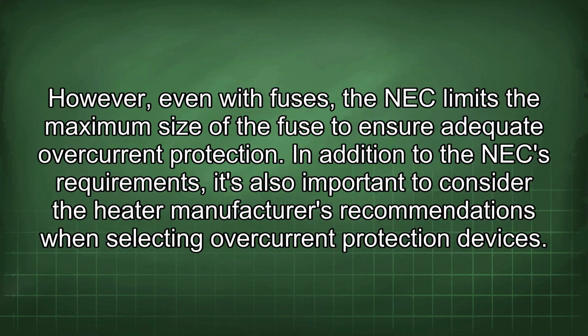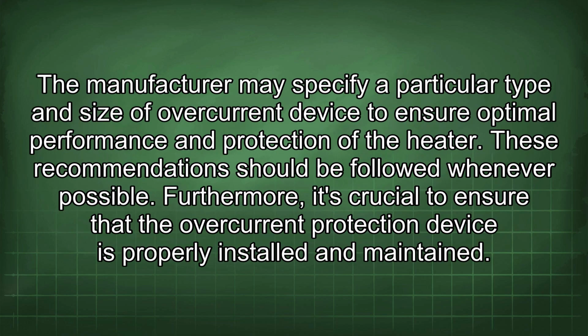However, even with fuses, the NEC limits the maximum size of the fuse to ensure adequate overcurrent protection. In addition to the NEC requirements, it's also important to consider the heater manufacturer's recommendations when selecting overcurrent protection devices. The manufacturer may specify a particular type and size of overcurrent device to ensure optimal performance and protection of the heater. These recommendations should be followed whenever possible.